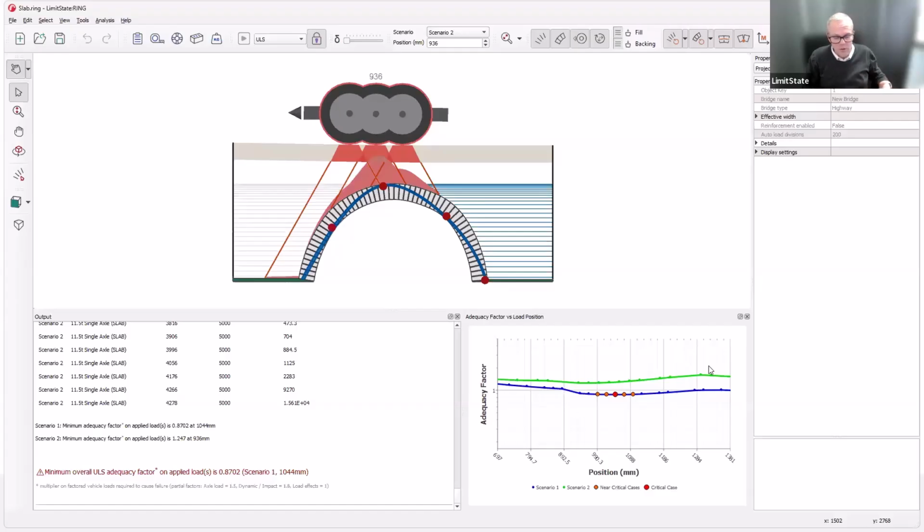But again, this is something that you would need to be able to justify from an engineering point of view. Similarly, if you've got a slab that lies over cracks or joints within the structure, then you could potentially consider that it negates the effects of the crack from stopping that load spread from getting to all parts of the arch. So again, you might be able to increase the effective width that way.